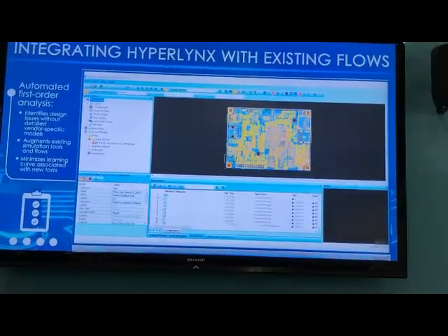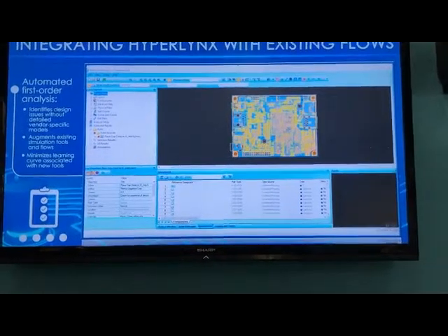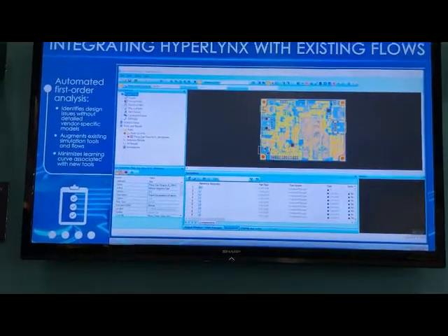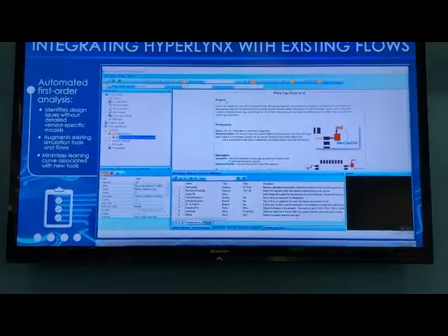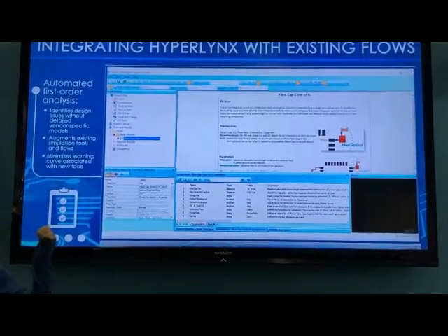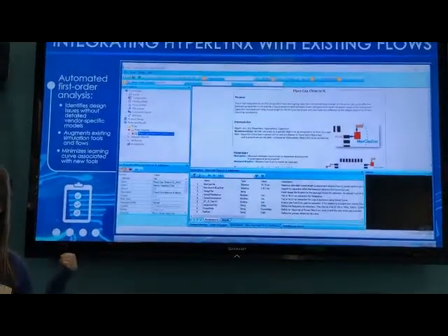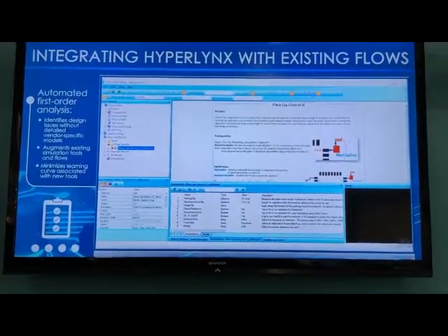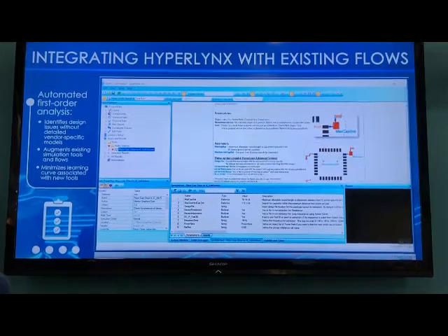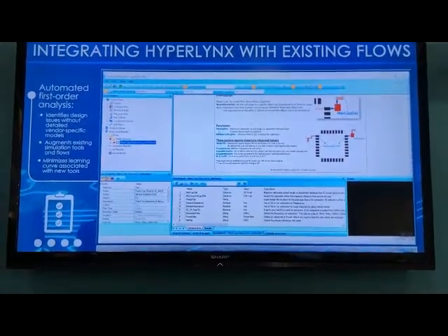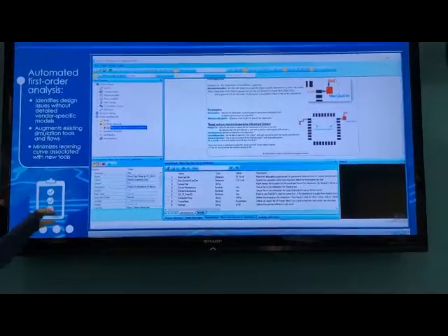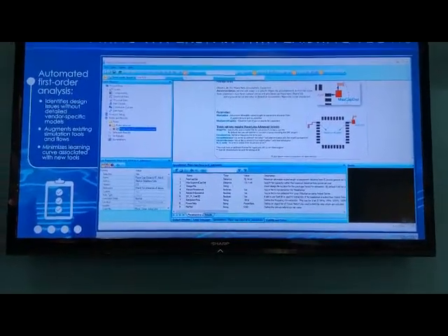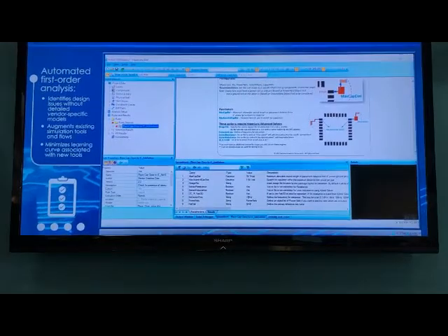Here's an example where I bring an actual board in. Now I want to make sure that I don't have to do much setup, right? So we want to configure this in a way that whoever opens a board, whatever project it is, it's set up automatically. I select that rule we were talking about, the capacitors being close to an IC pin, and all I want to have to do is determine what is my search distance around that pin, right? So these are parameterized. I define the search distance so the tool knows where to go look for those capacitors.